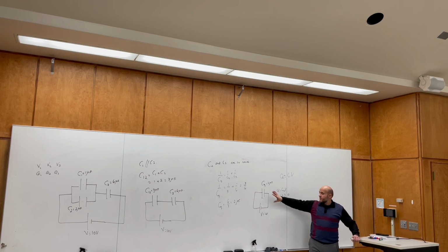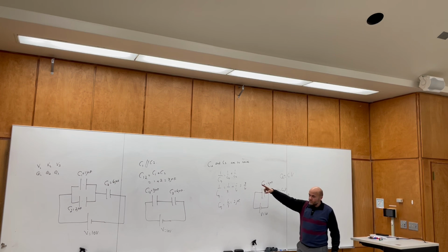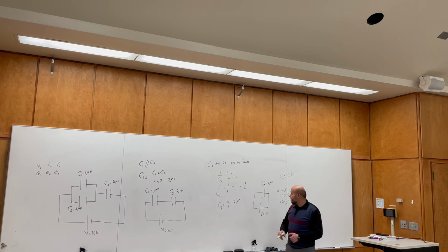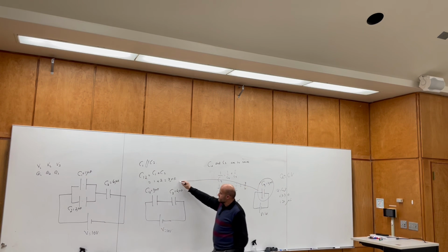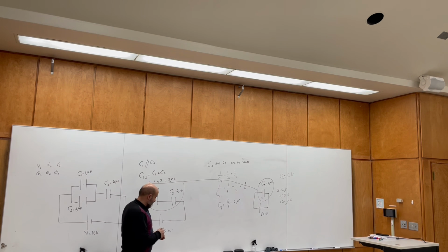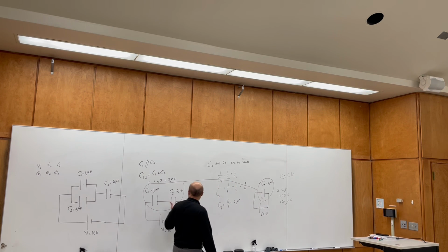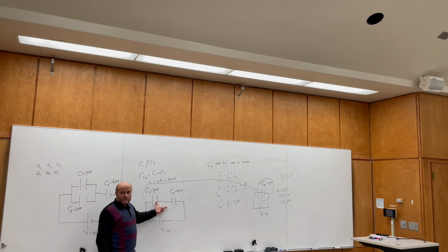So I know this capacitor has 20 microcoulomb. I know the voltage is 10, I know the C is 2. So I have everything for the circuit. But my question is, to find these numbers, not here, I have to go back to the first one. So now I will go backwards. I will go from this one to this circuit. And I know this capacitor is an equivalent of 2 capacitors that are initially, they were in series.